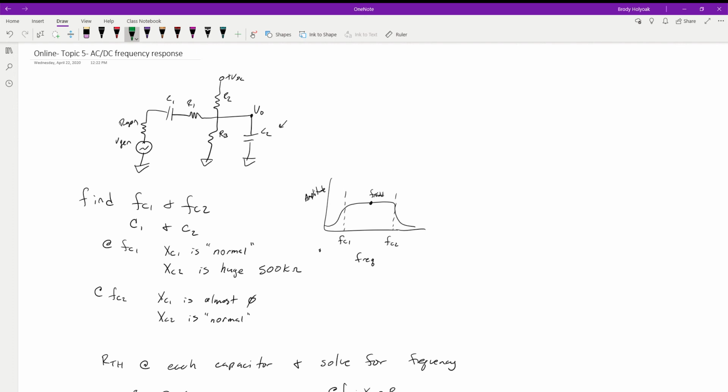I had one of my students last semester, his brick died for his computer, and he didn't have a replacement. It was on order and it was coming. And so what he actually did is he built his own power supply temporarily to power his laptop while the replacement came in. Now, I don't necessarily suggest doing this. He was okay with it, and I warned him about it because it was an older laptop, but he had some stuff on there that he was using, some spreadsheets and whatnot. I told him, with that, it's not regulated. Like if there's a spike or something, that power supply could take out your computer because there's no protection circuits in it.